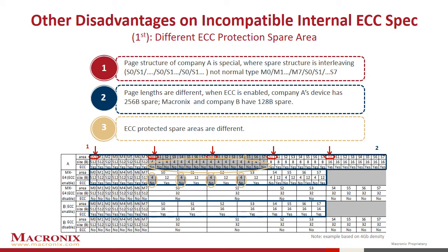One topic I have not touched so far is standards. In the parallel NAND market, most vendors support the ONFI standard. There is no such standard for serial NAND, which can lead to spec differences between different vendors. For example, each vendor may require 8-bit ECC error correction, but the spare area may have different portions or regions which are protected by the ECC.